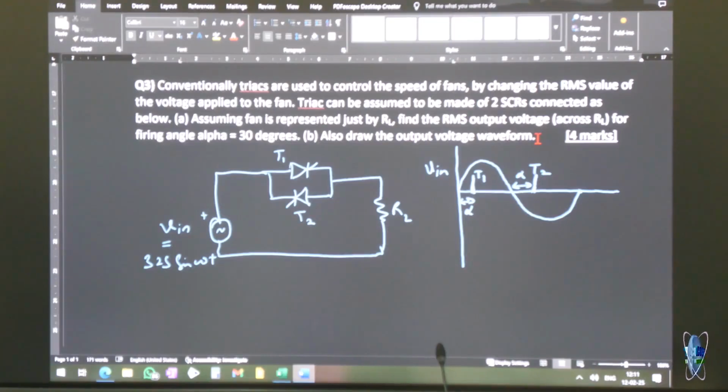That's one way. The other is, instead of using the resistance in between, you can put capacitance in between, because anyway this is an AC circuit. The drop was created by resistance; a capacitor will also create a drop. But in addition, a capacitor will not have any I square R losses, right? So you can do a capacitor switching. This is what most of the regulators these days would have.